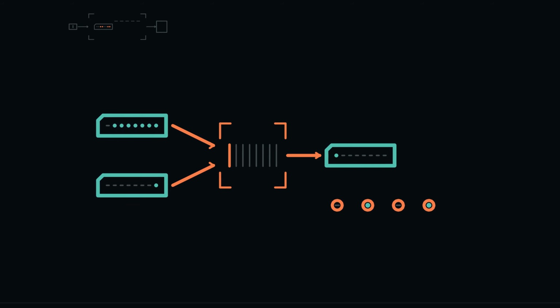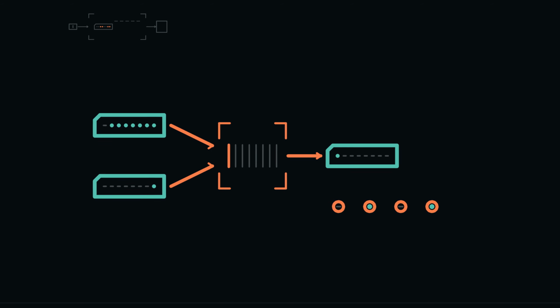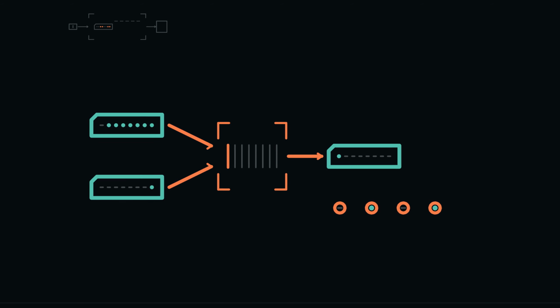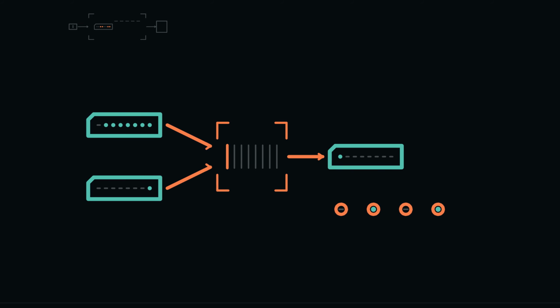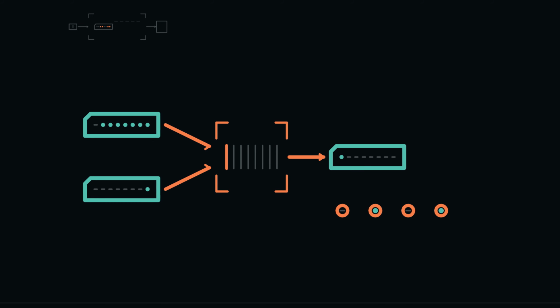Hexadecimal FF plus 1 stores 0. Carry is set because a 9th unsigned bit was produced. Signed overflow is clear because signed negative 1 plus 1 equals 0.